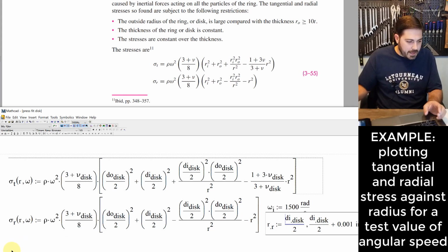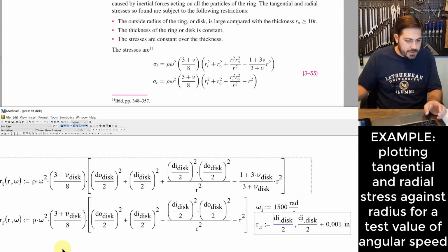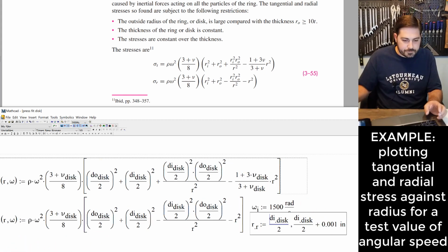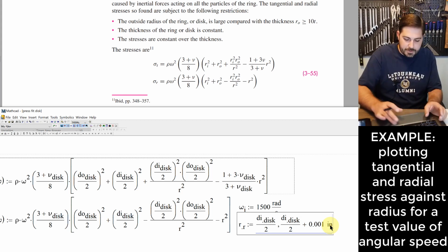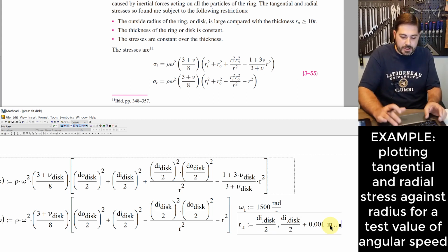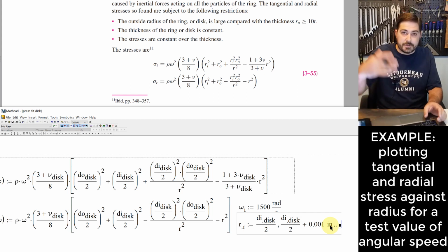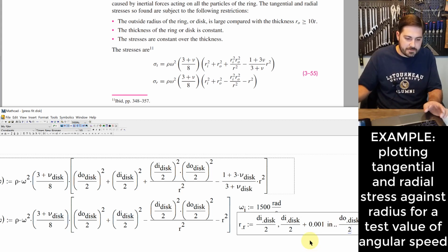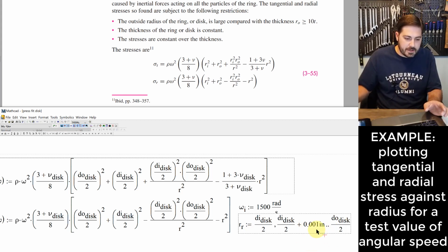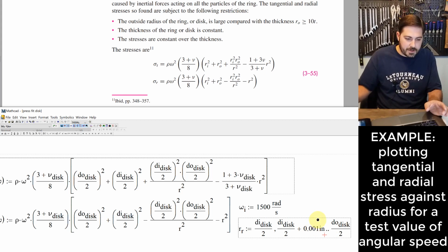Okay, and then the way these range variables work, the last term that you put in your range variable after your dot dot, which you get with a semicolon, is the highest value that it's going to be. So do for the disk over 2 is the last value that I should have in this series that I'm establishing with this little range variable.